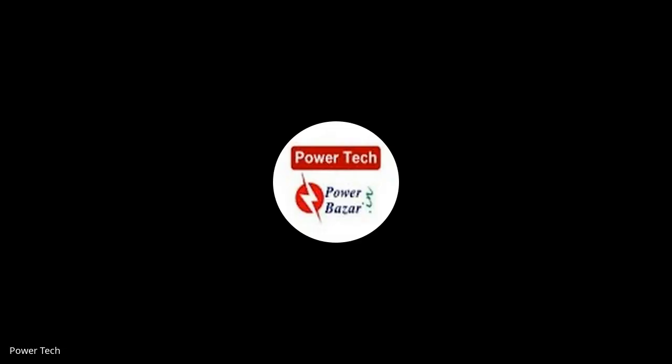Ajay Joshi ji has again told that arc furnace generates second harmonics, and why are our harmonic filters not grounded, third harmonic filters not grounded? Arc furnace generates second harmonic, your views? Practically we have seen that, and we have given a very big solution for arc furnace also. The second harmonic generation is there, but it is not going to an extent where it is unmanageable or creating any problem. We have not given any second harmonic filter. They don't want any active filter also.